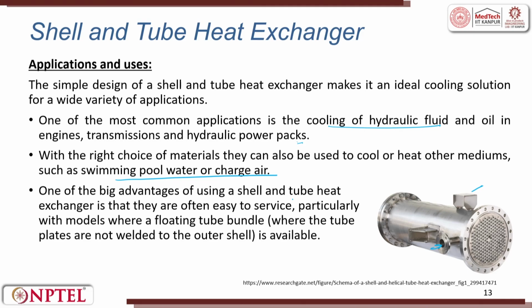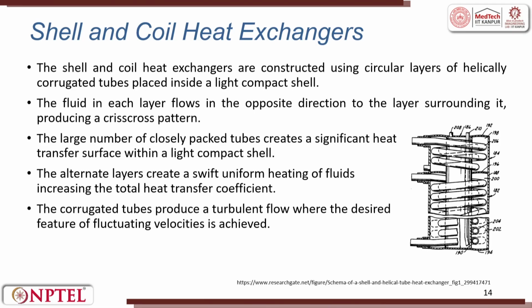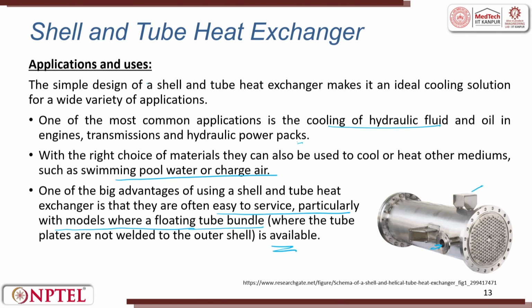One of the biggest advantages of using a shell and tube heat exchanger is that they are often easy to service, particularly with models where a floating tube bundle is available. So, for example, after a period of time, the tube can be choked. The fluid on the top which flows can deposit salts on it. So, it is also required to do maintenance. So, shell and tube type exchangers are very easy for it. This is shell and tube.